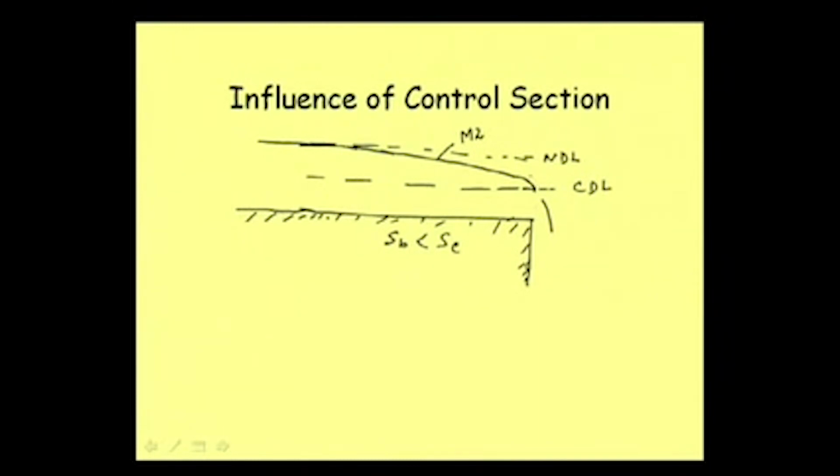Now, at the downstream point, this is also called brink depth or end depth, and from a practical point of view, as hydrostatic pressure is not prevailing here, that assumption was there for hydrostatic pressure. So some investigators analyzed that the brink depth or end depth is not exactly equal to critical depth. There are some differences, but approximately we can consider that this is equal to critical depth. Now from here we are starting, say critical depth, and this is our downstream point.